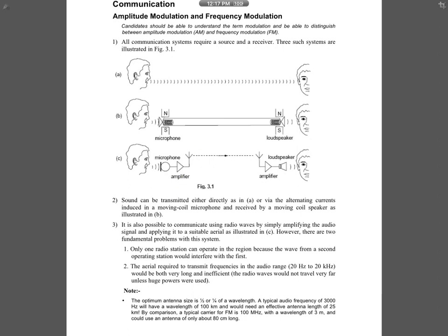That's it. There's no other special equipment needed. Microphone, amplifier, strip of bare wire, that's it. You will get your radio waves transmitted. Then on the receiver side, if somebody wants to listen to your signal, you will need another bare wire acting as an antenna or an aerial.